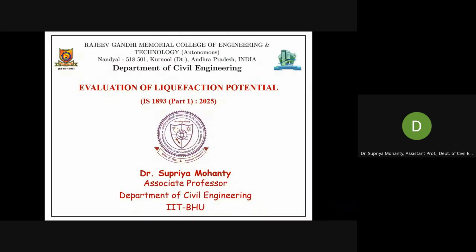Before discussing the codal provisions, I will first cover the introduction, the basics of liquefaction, why it is important, and why liquefaction study is carried out nowadays for all important critical structures, which was not there in our previous code, like the 2002 version. Liquefaction potential evaluation was not there, and in 2016 it was included as an appendix, and now in 2025 it has been included in the general provisions, that is Part 1.